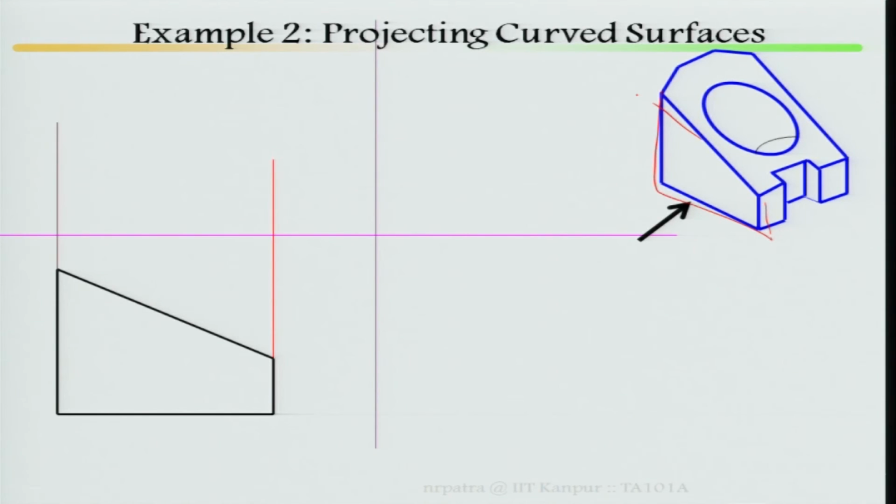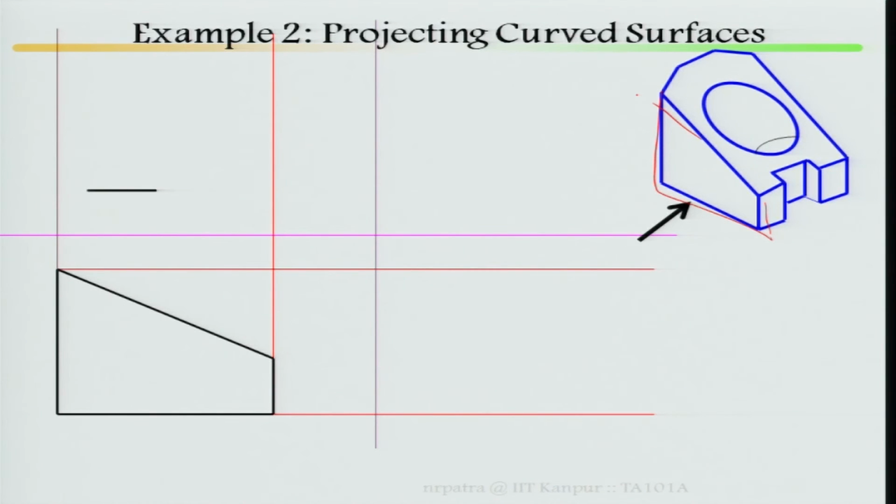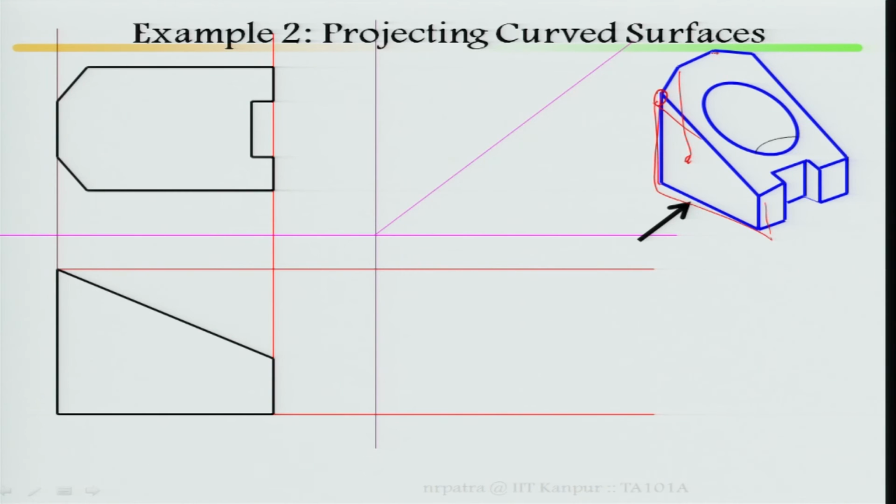Then mark it in the top view, which part you can see very easily. This top view you can very easily mark, because once you are looking at the top view, this point and this point will merge. Similarly, this to this point will merge, this to this point will merge, it will come as one line in these directions. Then mark your side view.